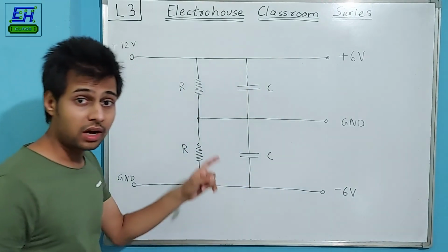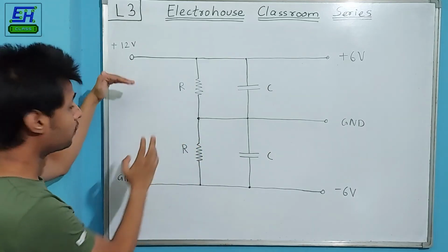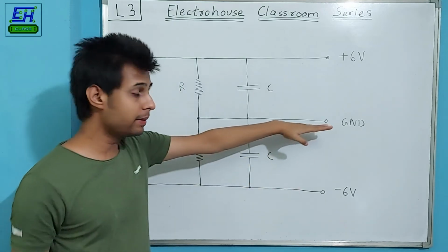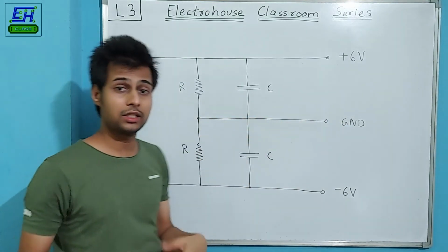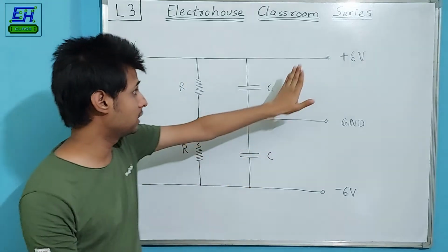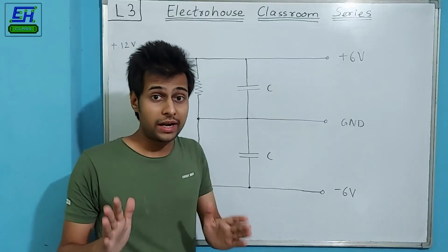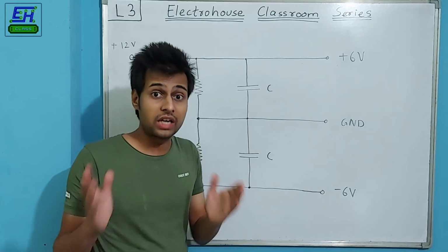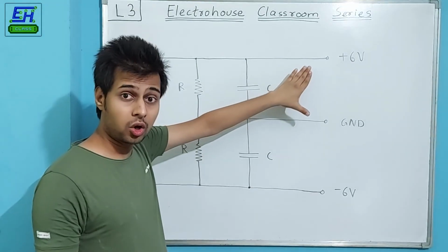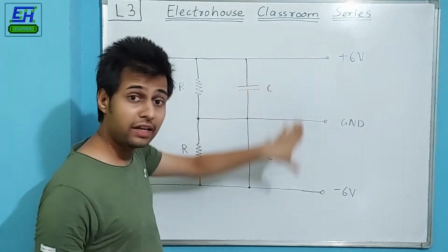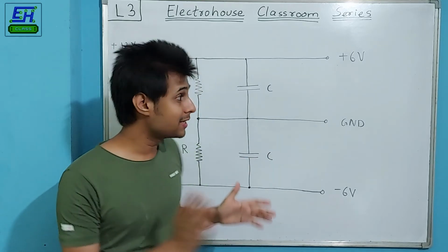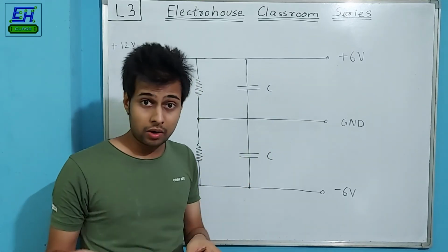and it will change the voltage at this common point, which was earlier expected to be somewhere in the middle of the input supplied voltage. Like in this example, it will definitely be greater than 6 volts, like 6.5 volts, 6.8 volts, or 7 volts. It actually depends upon the load which we are connecting. So ideally ground should be constant, which is referred to as 0 volts. But here, as you know, the load is changing, or you are connecting loads unevenly, then definitely your ground is also going to be affected, and hence this is not a well regulated dual power supply.